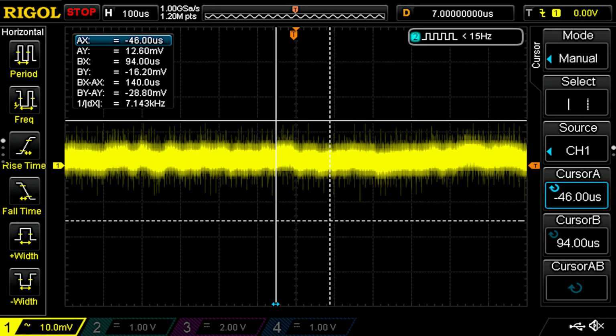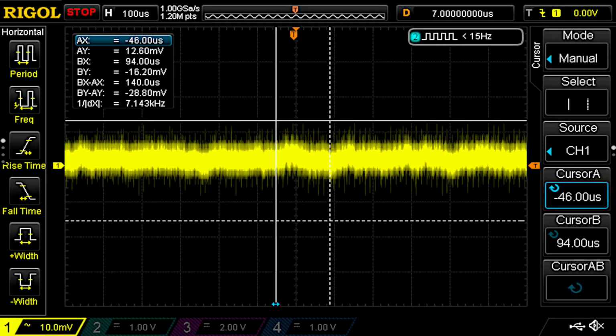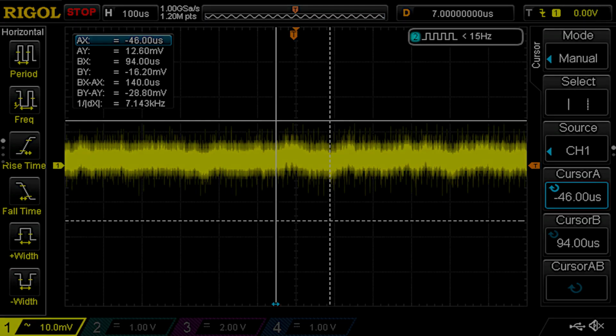This is what my plus 5 volt rail looks like now. The gain on the scope is wide open. I don't think that is too bad. This is the 1.2 volt band gap reference voltage. It runs off the 5 volt line, so maybe that's why they look quite similar.